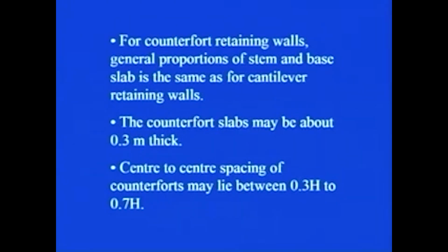For counterfort retaining walls, the general proportions of stem and base slab are the same as for cantilever retaining walls. I already mentioned to you that the counterfort retaining wall is a particular type of cantilever retaining wall. Now, how can you provide these counterfort slabs? There are various specifications available in relevant IS codes, but they are a little bit more advanced studies, so it is beyond the scope of our course. So, you just note down these guidelines.